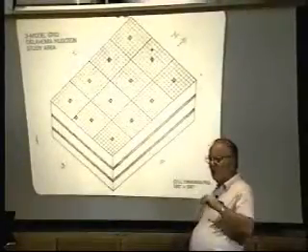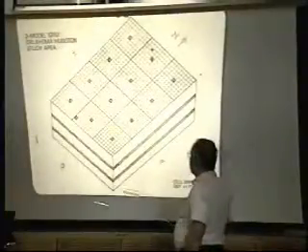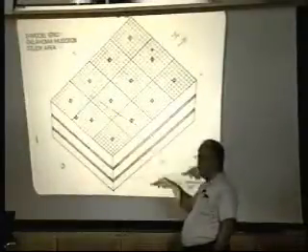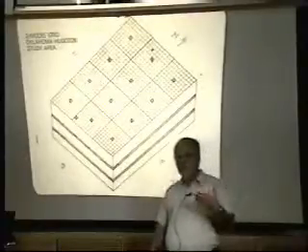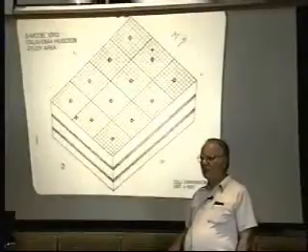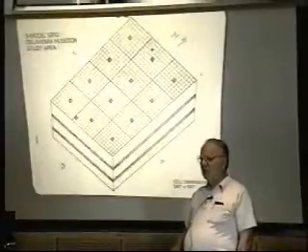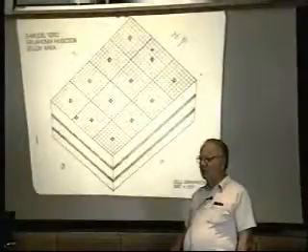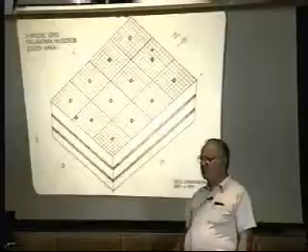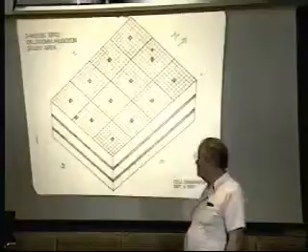After we got it matched, then we opened it up to see what the effects would be of crossflow. We did some initial studies to demonstrate that if we had a 9x9 grid within a section, that we could simulate the 72-hour shut-ins and a 72-hour drawdown. This is going to be our history matching. You're going to match the pressure versus Qm and the official deliverability tests. Again, the pressure versus Qm basically matches the in place, or the gas in place, and the deliverability is going to match the KH and skins on the wells.